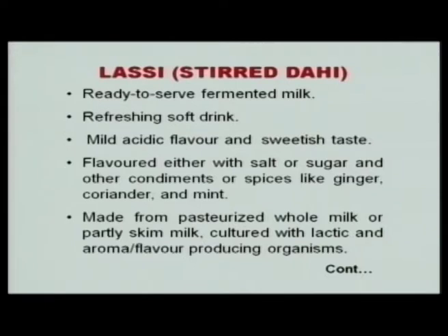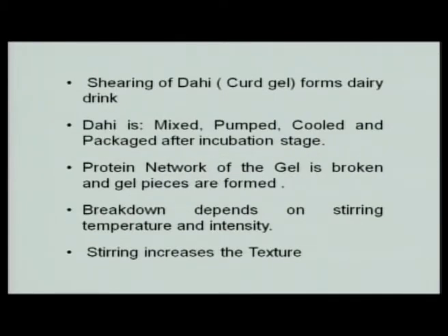Now, when we say lassi, we have seen the production chart, but it is a ready to serve fermented milk product. It is a soft drink, it is mildly acidic in nature, and it can be used with spices also. It is basically shearing of the dahi, and it is mixed, pumped, cooled and packed after the incubation stage. It involves the protein network of the gel being broken and gel pieces being formed. Now, breakdown depends on the stirring temperature and intensity, and the stirring increases the texture.